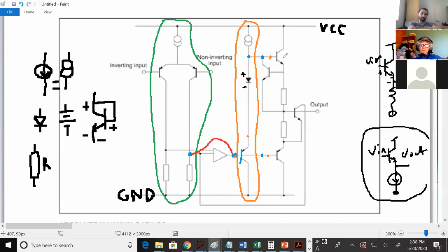The way to figure out what voltage you need is to follow the push-pull from this base to here, that's 1 VBE on drop. If you're ignoring the resistors, then you have a second VBE on drop. So the drop across here, to put both of these on the edge of conduction, has to be the same as the drop going this way. The loop this way and the loop this way should have the same voltage drops. Then you won't have crossover distortion anymore.